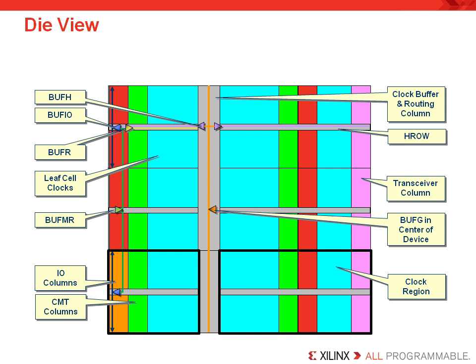Now, there are also regional clock routing resources called BUFRs. In addition to clocking elements in a single clock region, a BUFR can also drive clocks into some of the neighboring clock regions, but usually, again, only specifically to a region above or below. The BUFIO I/O buffers are placed within the I/O column and are designed to drive the I/O clock network just in that bank. Now, some BUFIOs are capable of spanning multiple clock regions.